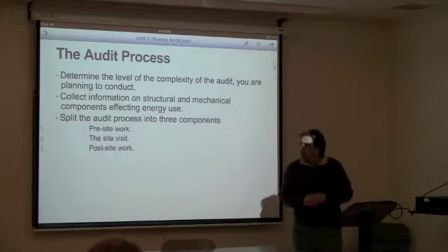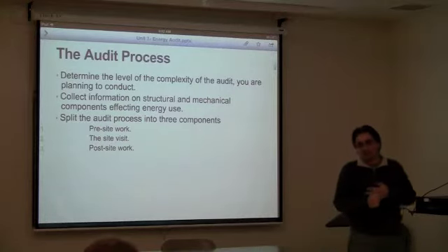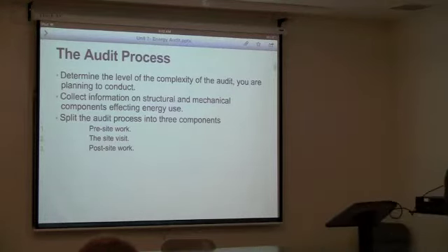Energy auditing. You have a pre-site work, you have a site work, and you have a post-site. Pre-site work is you get your energy bills, you try to map out the building, you try to find out where the energy usage is, and try to collect as much information as possible from the blueprints of the factory or residential house, talking over the phone with the managers.